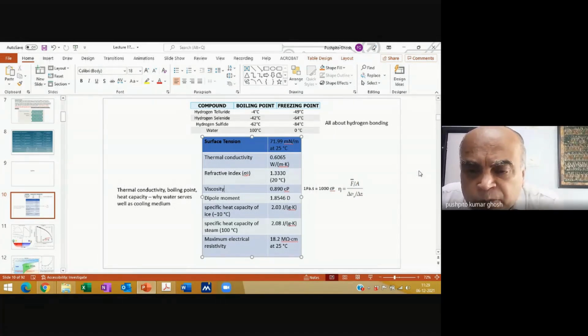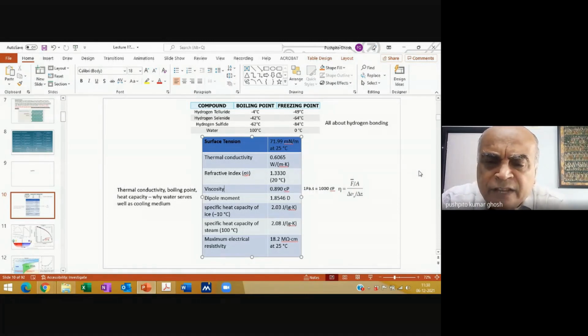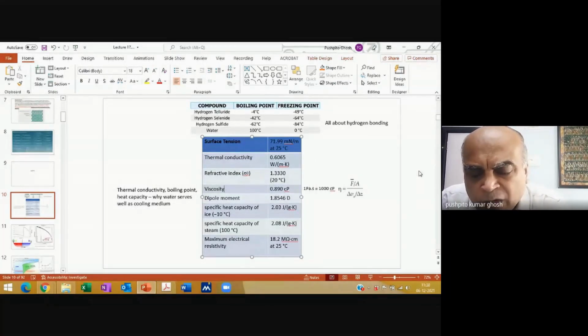But it is an obstruction which is created by itself. In other words, if I look at, let's say, the flow of liquid in a pipe, I can look at layers and layers of water, and if, for example, one layer of water is not able to slide past the adjacent layer of water, which can happen because of frictional forces, then basically that is the obstruction that it is creating.